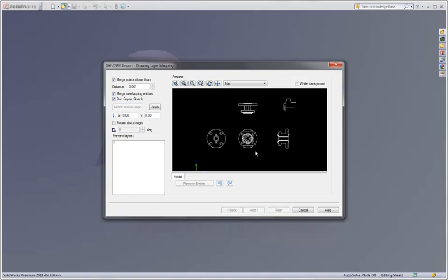And finally, there's the option to redefine the sketch origin. This is where it's going to be brought into my part file. This is nice because with a lot of 2D files, your DWG data ends up way off of the origin and you end up having to move it anyway. So it just saves me an extra step.